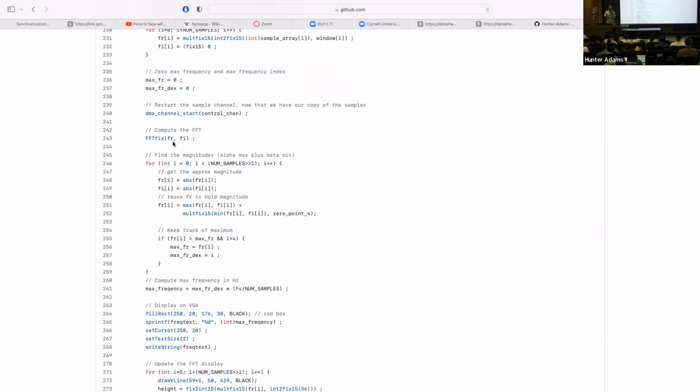It is entirely possible that the state of your crickets change from when you started gathering the ADC buffer to when you stop. So if you only asked for the state of each cricket when you started gathering this, core 0 may say, I'm not producing a cricket chirp, but then right after you start gathering the batch of samples, it starts producing a cricket chirp. So you'd have a whole batch full of core 0's cricket, but you would be under the impression that core 0 didn't produce that cricket chirp. So you need 2 pieces of information from each core. Which state are you in, and how much longer will you be in that state?